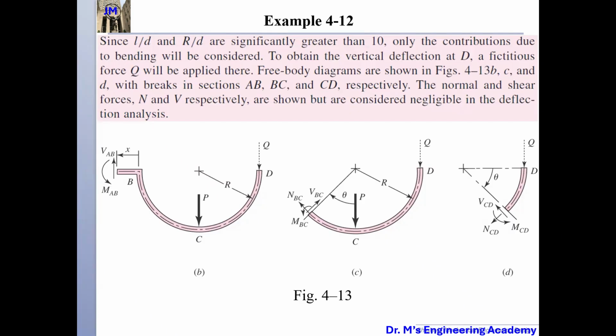And so dU1/dQ we will have 1/EI, this is EI, then this is M1. For M1 I use MAB to denote. MAB, then dMAB/dQ, and then I have R, then R dθ.